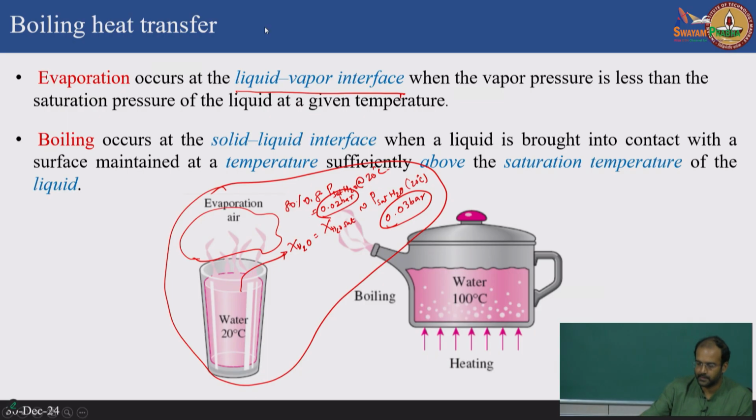Okay. So, this pressure difference, this partial pressure difference, is related to the concentration gradient, because when we write down the equation of state, we are assuming, let us say at 1 atmosphere, water vapor can be treated as an ideal gas. So, you have PV is equal to nR_uT, where R_u is the universal gas constant, n is the number of moles and V is the volume. Therefore, n by V is basically your molar concentration, and that is given by P by R_uT.